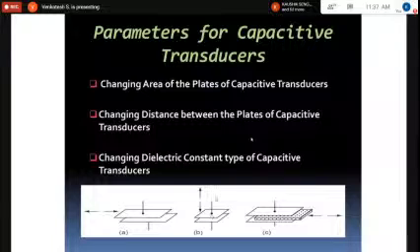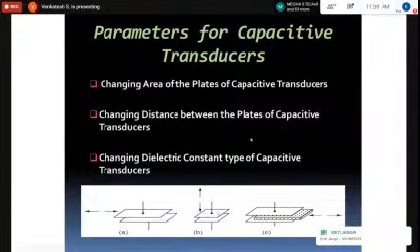Therefore, if C is changing, reactance is changing, and then the voltage drop across the capacitor, which depends on the capacitive reactance, changes. AC resistance is reactance. Like in a potentiometer, where we have a change in potential with change in displacement, that is the transduction we are realizing using just two metal plates, one above the other, as shown in the diagram.